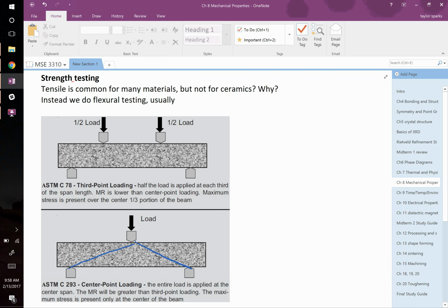And then when you do 4-point, that load is essentially spread out between those 2 points rather than this. Yep. If you were to plot the bending moment, which is proportional to the strength of the material, right? You get a larger region, say 6 millimeters versus just one spot, right? And so then, why does that influence strength? So your maximum bending moment is whatever the value is here, or you reach the same value there, so why do you get different strength?